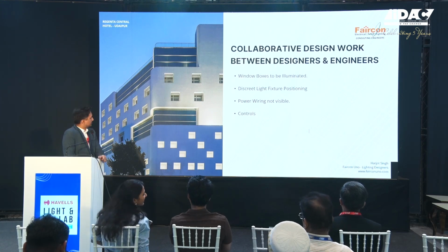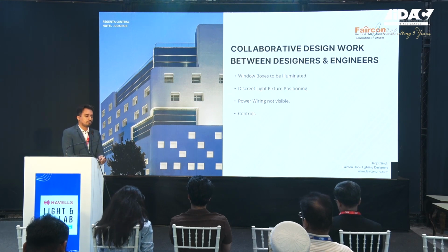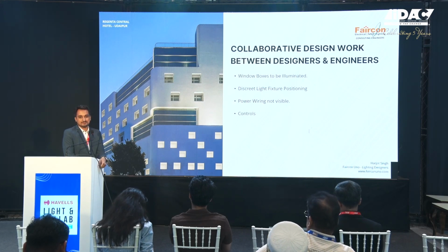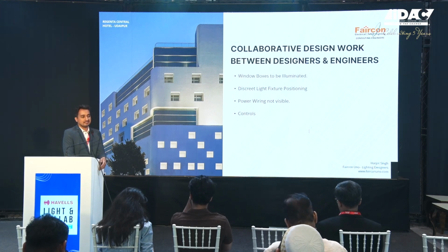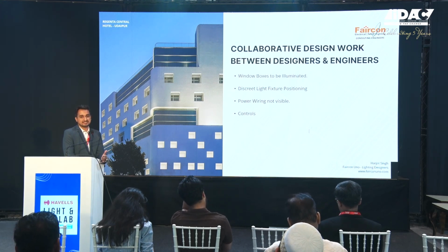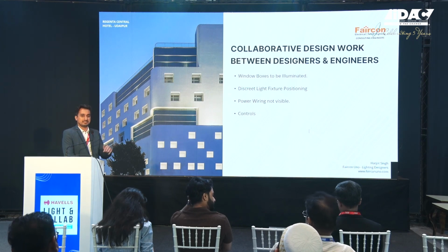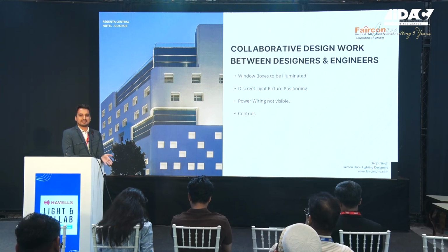And at the same time, we had to play with glare, like Ashish mentioned, not coming into the window of the guest. We don't want them to draw their day curtains during the night. So that was another asymmetrical fixture that we had to come up with along with the OEM, where the illumination is to the windowsill, but not inside the guest rooms. And when the guest is standing, it does not hurt their eye. So we had to block that out also.